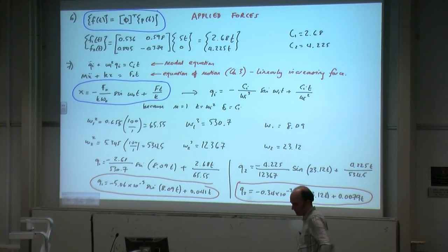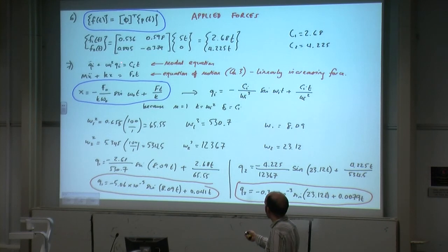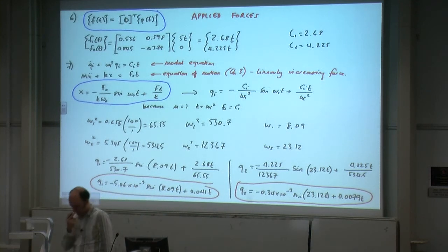And so what you do is the modal equation is always going to look like this up here, okay? For a linearly increasing force, you'll have some constant times by time. And we've solved that equation, but in this form in chapter 3. And the solution in chapter 3 we found to be this, for initial rest conditions. Obviously, if you haven't got initial rest conditions, you have to work out what A1 and A2 are from the general equation.